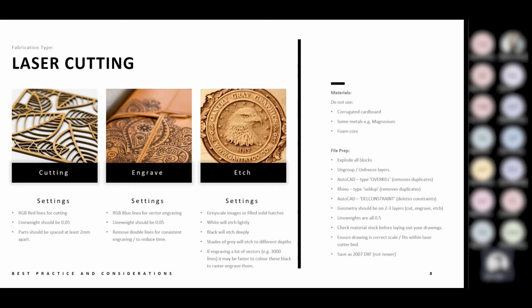Final things, of course, would be to ensure your drawing is the correct scale and fits within a laser cut bed. So it's very common to draw your objects at 1:1 scale if you get to scale them down. And of course, trying to fabricate that 1:1 is going to be very, very expensive. You need a very big machine. And of course, lastly, save as a 2007 DXF.